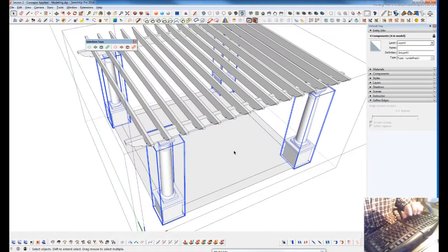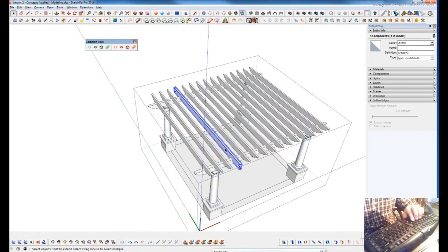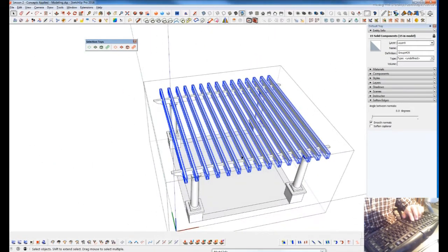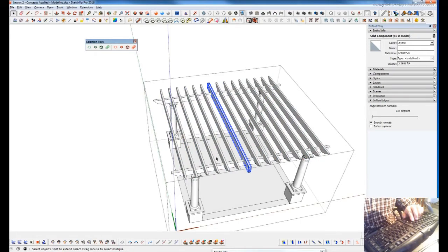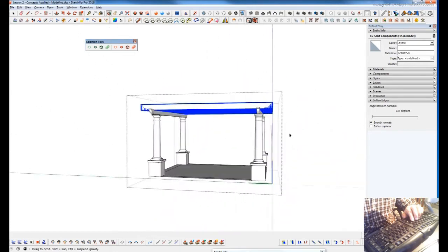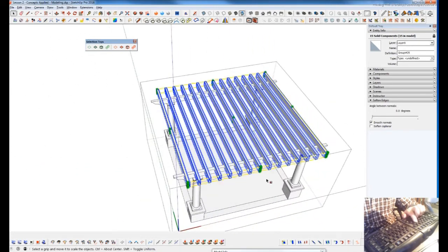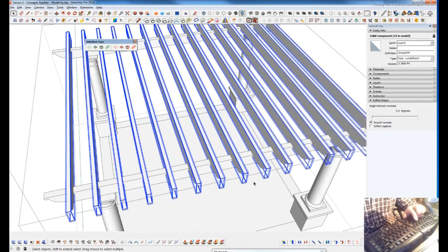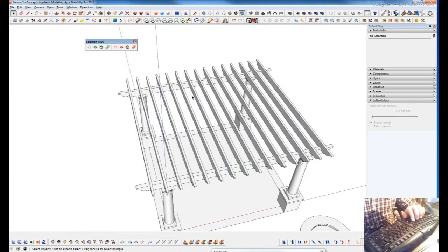That's a component. There's 4 in the model. Shift-A, I select all 4. Same with these rafters up top. With Shift-A, I've selected all of them. And instead of trying to move the camera back, move the camera, drag select, and then move the camera back, and then manipulate, I can grab one, stay in the same camera position, Shift-A, now I can scale.